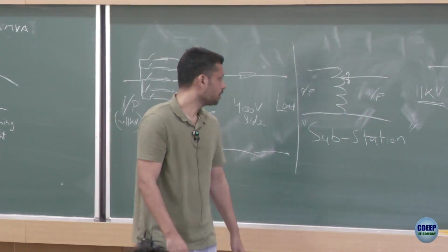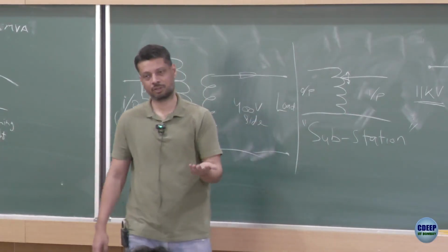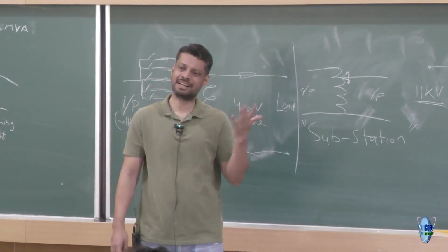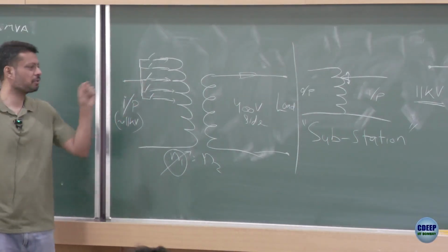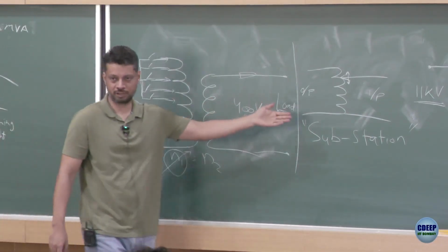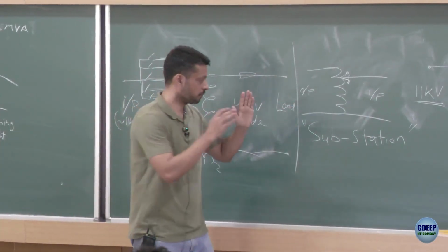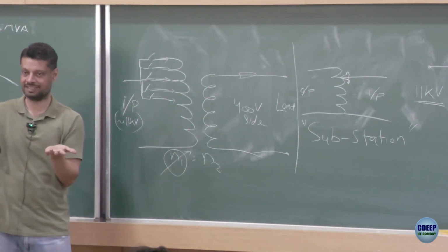Oh, no. Having one auto transformer extra is of course costly. You anyway have a transformer, you build a few more extra things, just take out a few more taps from the same transformer. Why do you want to have one more auto transformer? So, including it in the main transformer is of course much cheaper.